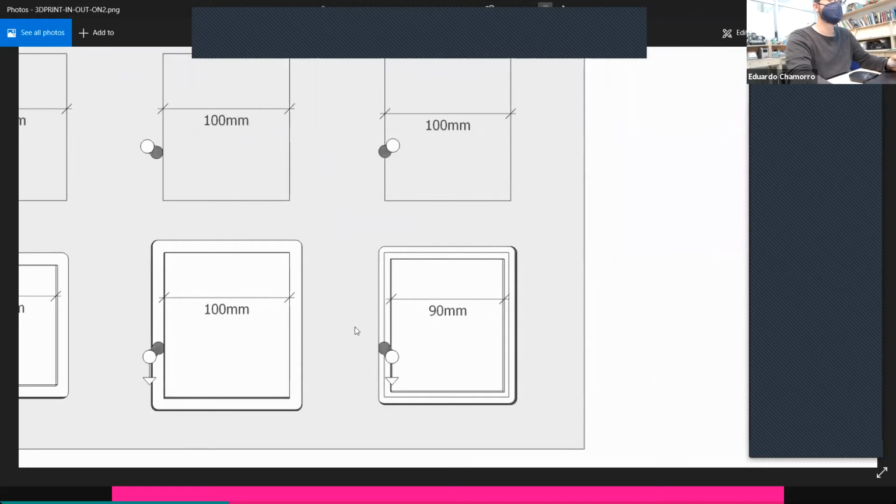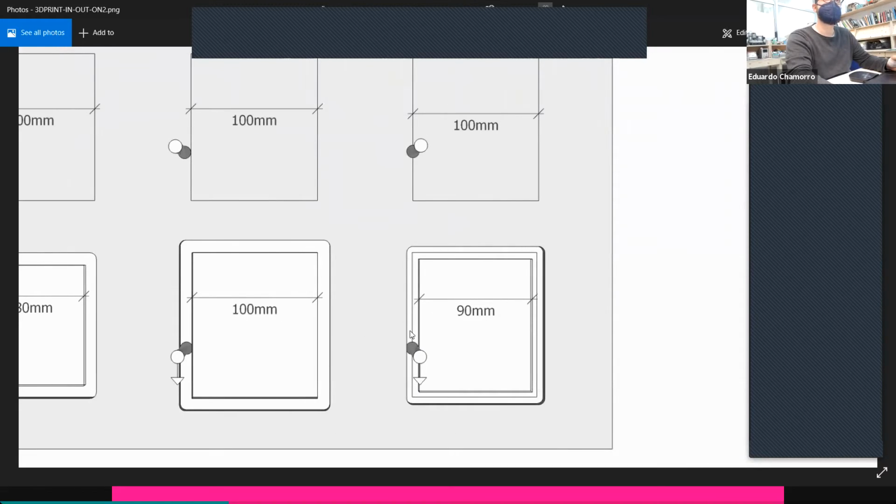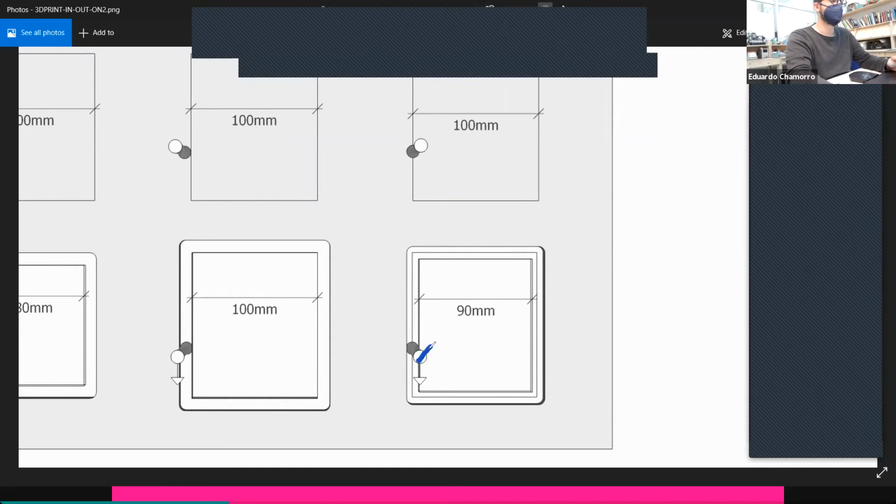If you want on cut, it's because in your design you're already accounting for the end mill diameter. If you know that this is a 6 millimeter, you know that you are eating 3 in this direction and 3 in the other direction. So if you actually want a 90 millimeter part, well, this is not 90. Let's say I'm using a 10 millimeter end mill, okay?